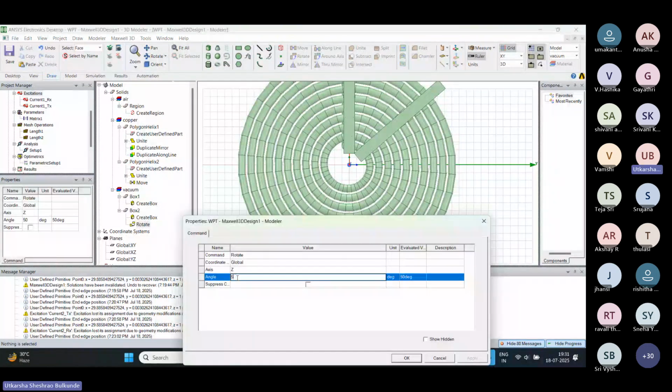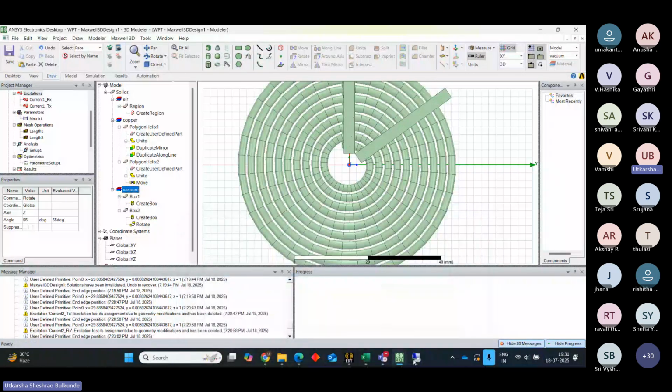In Ansys, no two geometries should intersect or else it will throw an error. Like it can touch, but it cannot intersect. It cannot overlap. Okay? Understood?